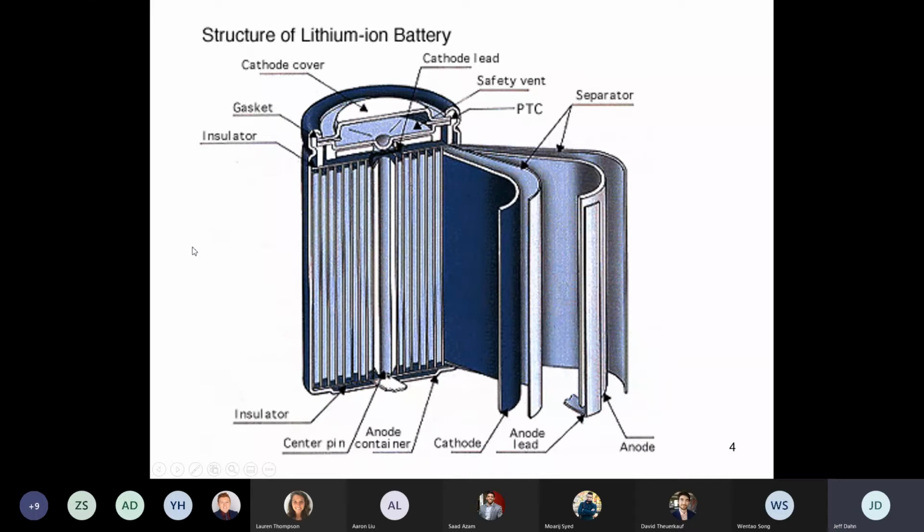That's called side rupture. And side rupture is generally very bad because if you have cells stacked vertically side by side, so the cell you see here is in vertical position, put another one next to it. If one has side rupture into the other, you have enormous heat that's blasting at the neighboring cell, and you can set that one off. So you really want cells to vent from the safety vent, and you don't want anything else in the way, so that if one cell vents, it's unlikely to cause propagation to the next.